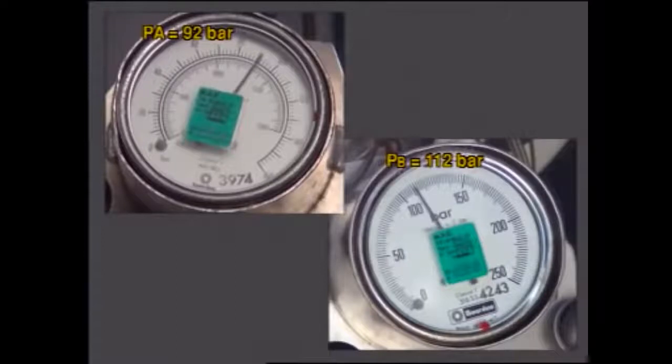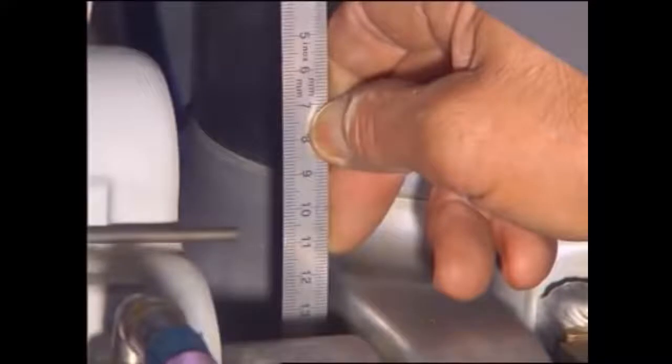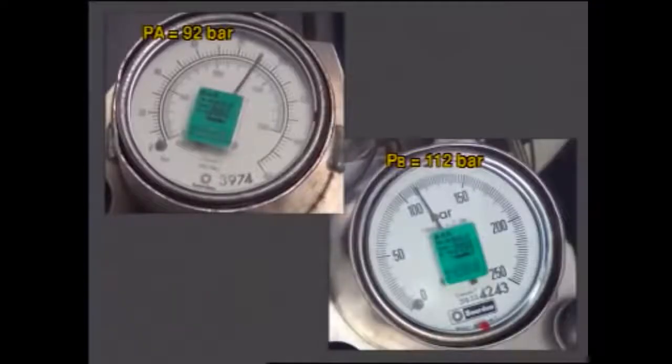Wait 10 minutes and make sure that the pressure condition between the two chambers is fulfilled. The pressure condition is fulfilled. The nitrogen pressure being released, read and write down the temperature again, as well as the dimension H. Make sure that the difference in pressure at the top charging valve and the bottom charging valve is more than 10.7 bar, this condition being enough at this point.